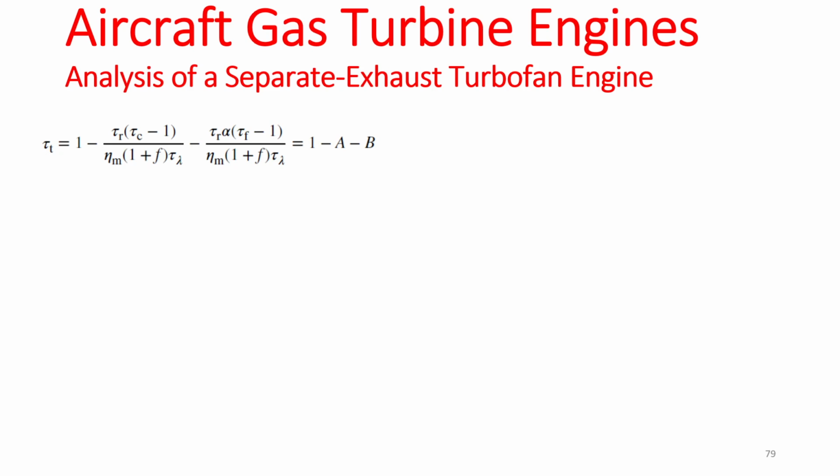But eventually, what you're going to see is that this term is going to be pretty small. Often, when you have a turbofan, the main contribution comes from this term, right? And there's one ratio in this term that can become 30, 40, and there are some designs that have those ratios. So the bypass ratio, yeah, the bypass ratio can be 30, 40.